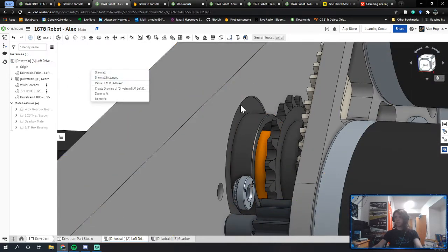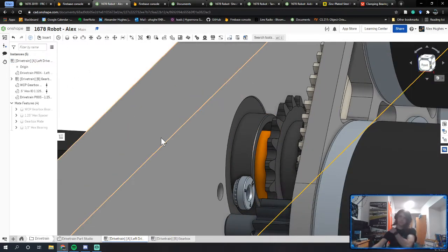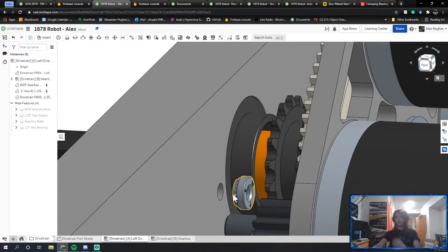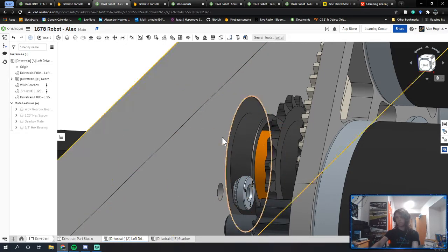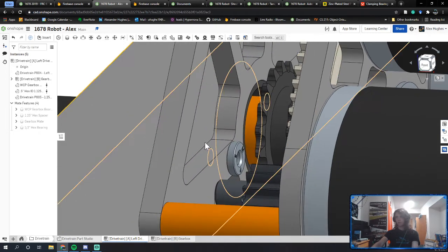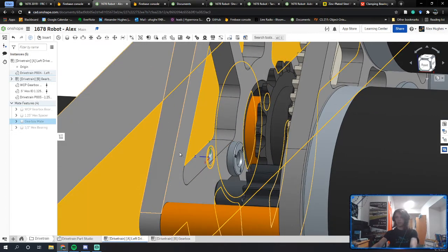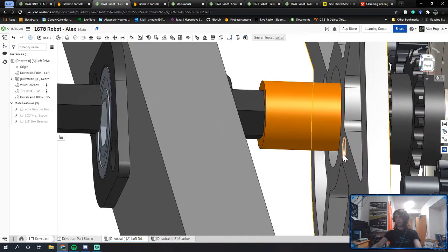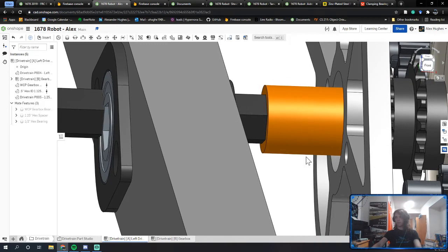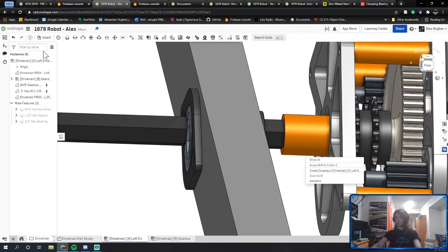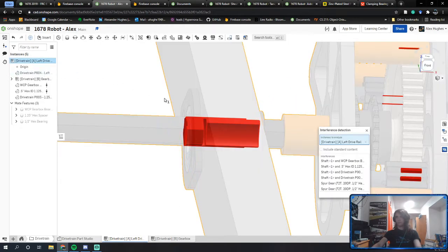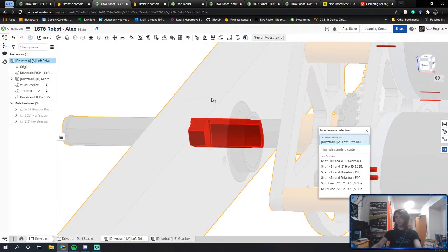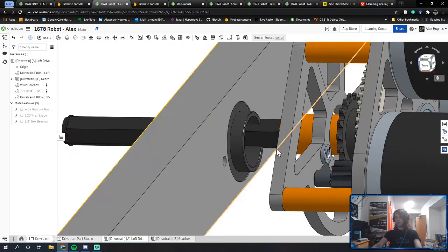Wait, how did you connect the gearbox to the actual rail? I mated the hole where you have that PEM nut. The outside of that is mated to the hole we drilled just to the left of this big hole. So, let me check that quickly. I mated this hole right here, this hole right here. Let me run a check. Now I'm not having issues with that.